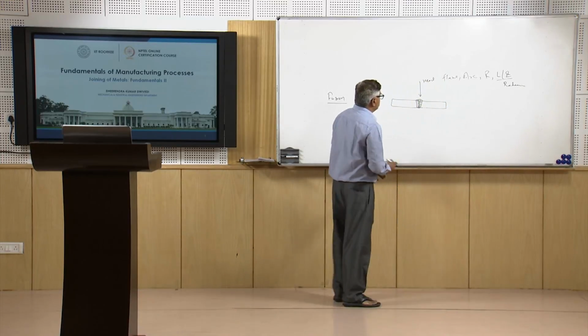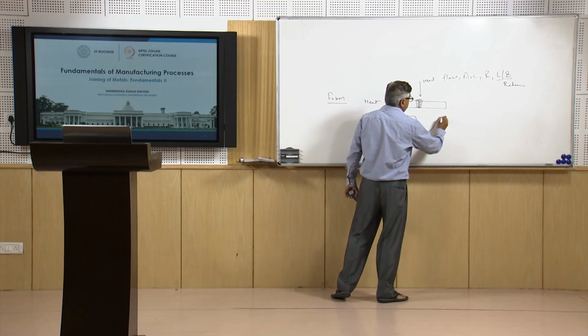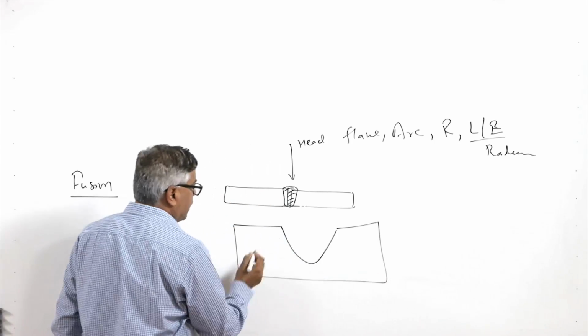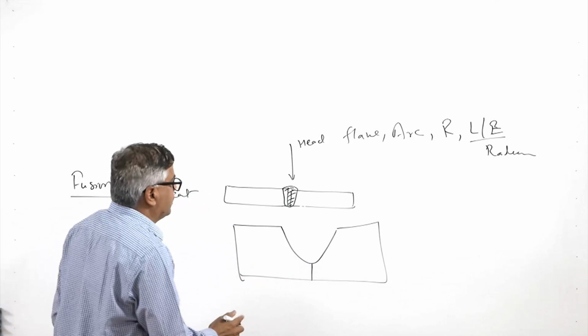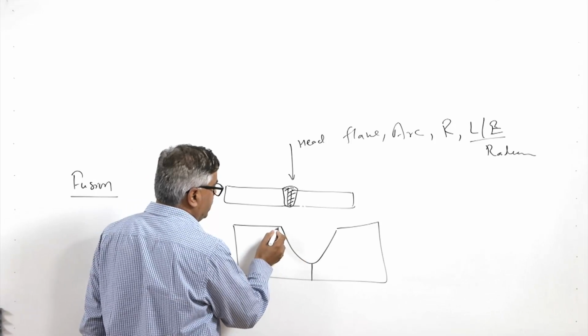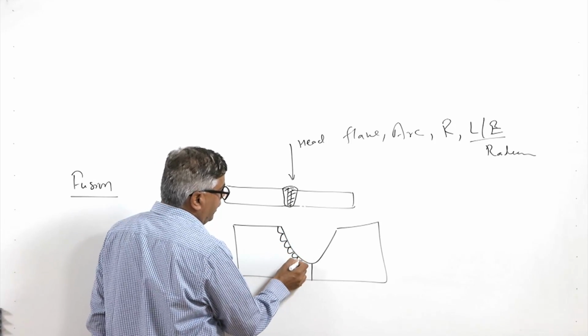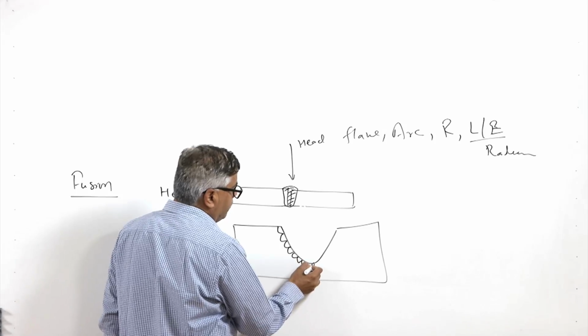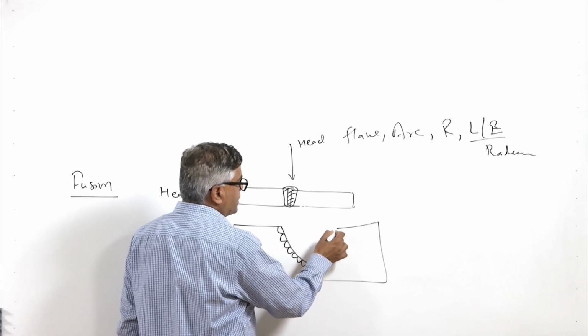In this situation, when solidification of the weld metal takes place, where the faying surfaces have been brought to the molten state, there will be a number of unmelted grains, and the molten metal is of the same composition.